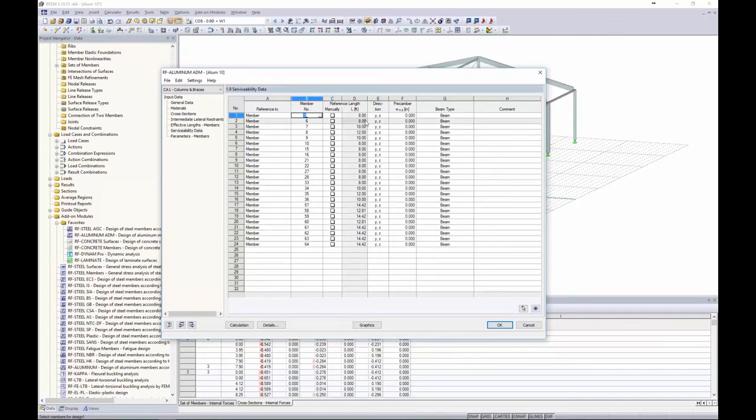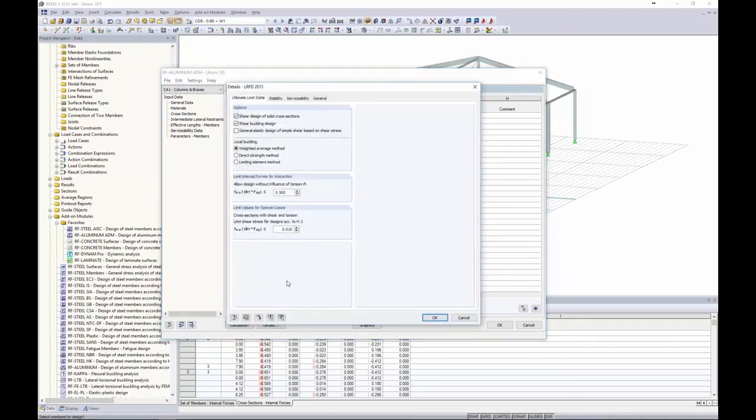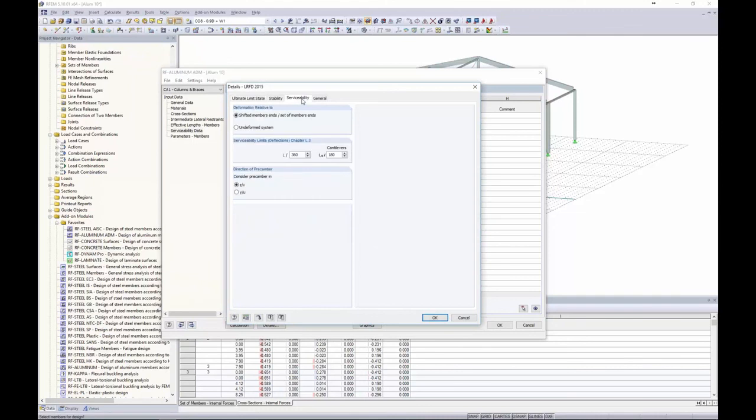Now we can also add in the reference length, again defaults to the full member length, but we can also manually change this if we'd like to. I'll again show that in my next example. We can add in a pre-camber here if we'd like to, and lastly we just specify whether this is a beam or cantilever. So the question is, what is this deflection check comparing it to in terms of our limiting deflection ratios? Well, that's under the Details tab again and under Serviceability.